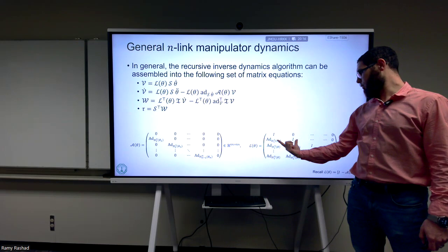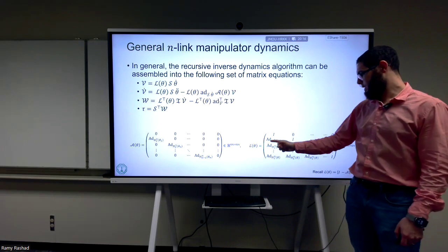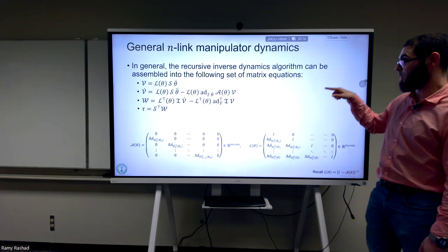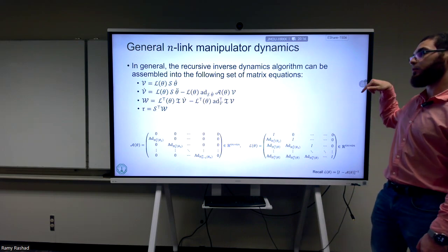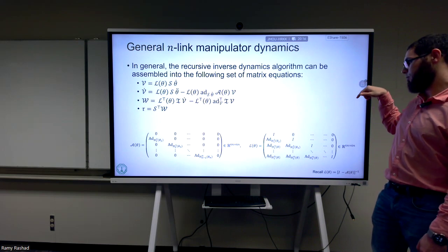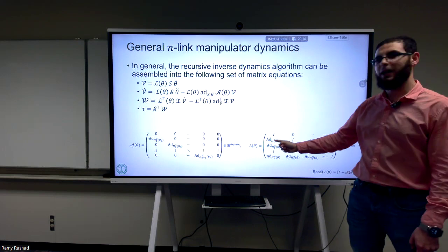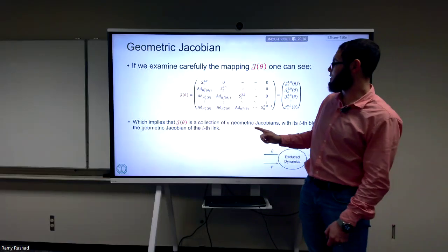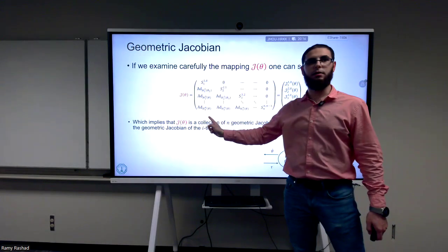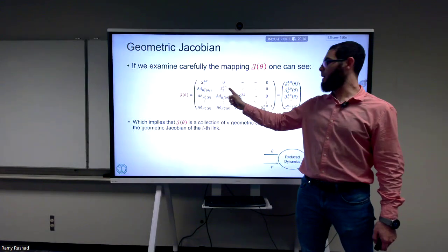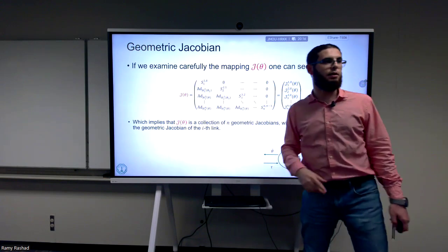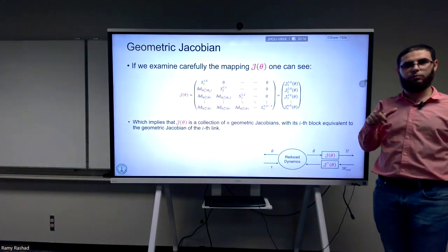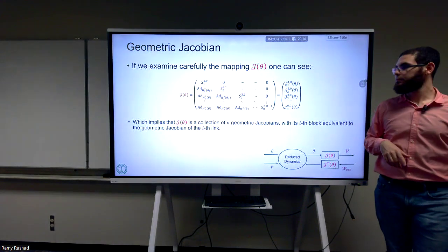But when I multiply this one, column by column, the adjoint with the first S, this one will multiply by the first S. So the S that appears here will also appear in all of these, and the S that appears here will appear in all of these here, and so on. And then you get back the expression that we had for the Jacobian. Very good point. I'm going to correct this in the slide.